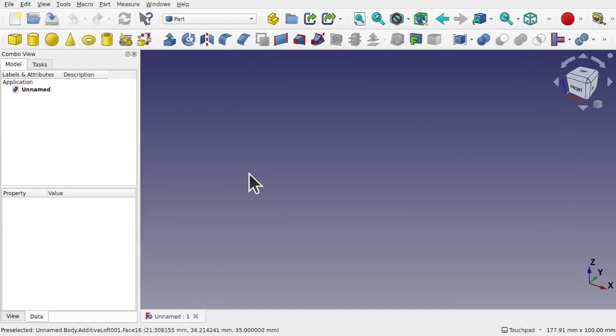For our next loft workflow, we're going to be using the part workbench. The reason why we're using the part workbench is because it's very versatile and very flexible with the different profiles that you can use with your lofting. For instance, rather than just using sketches and faces, we can use surfaces, vertices, edges, etc. in there. We're going to be using a loft to a surface workflow. And this comes in handy if we want to close the loft, but we don't want to close the loft to a point. We actually want to surface the closure so it's a feature in itself.